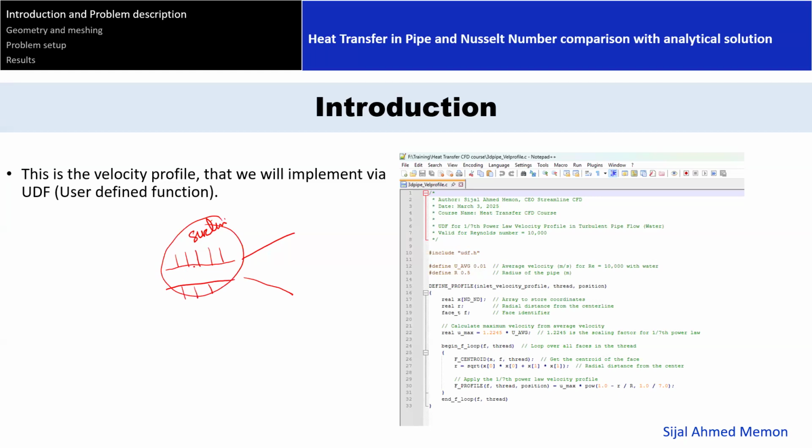Similarly, in the CFD, we do the same thing either by making this a slip condition, meaning zero slip or zero shear, and applying the boundary layer directly, like when the fluid develops, using the UDF here. We cannot do it exactly at the geometry entrance, because the flow will be changing much more here, its local conditions changing.